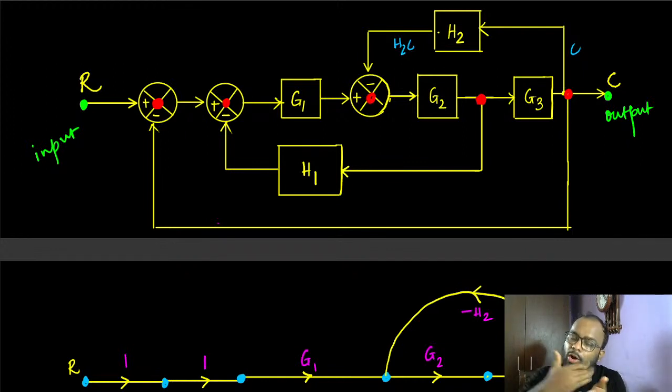But try to understand, in order to deflect the coil, the voltmeter itself is consuming some amount of power, and by consuming some power, it is dropping the voltage. Ideally you want to measure the EMF, but the moment you connect a voltmeter, some current is drawn by the voltmeter, and there will be a potential drop. So the voltmeter will always measure lower than the EMF, because the voltmeter itself is a load, drawing some amount of current.